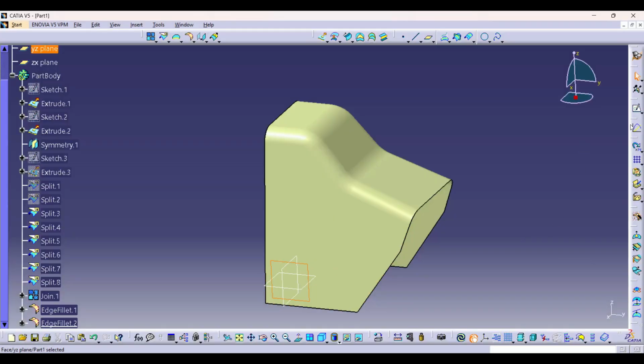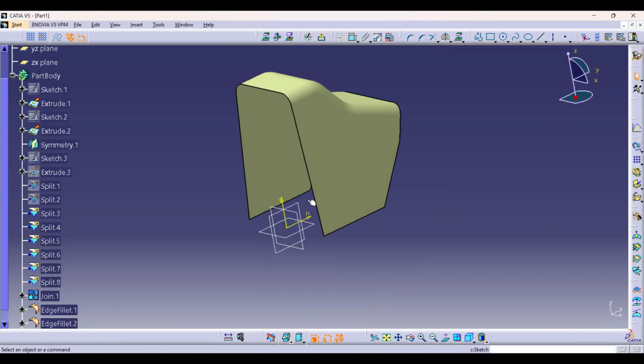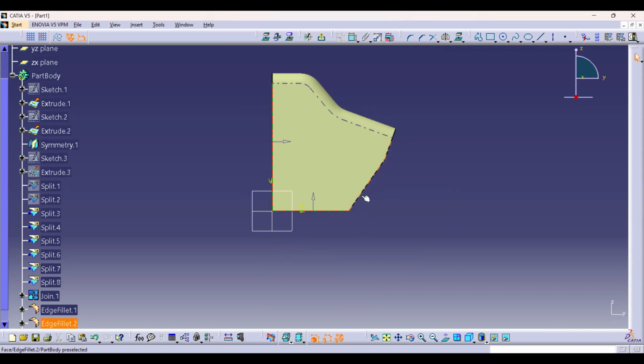Finally we will get the result as a fillet here. For that we are going to select this mid plane. Go for this sketch. Say project entities to both the edges. I'll say project here. Make them construction. They are for reference purpose for starting and ending the arc.